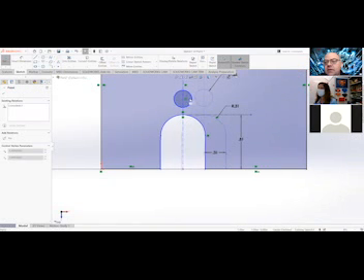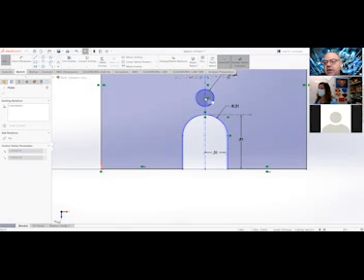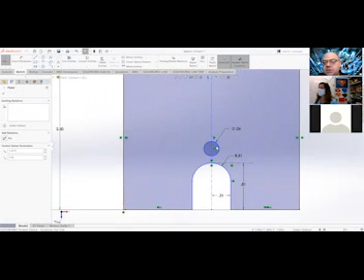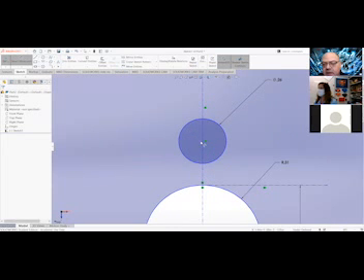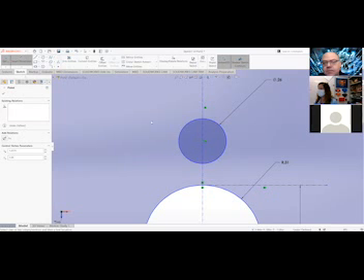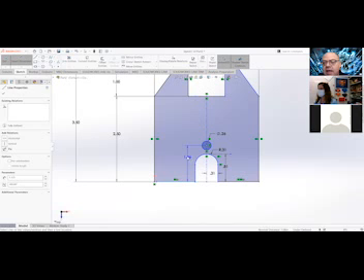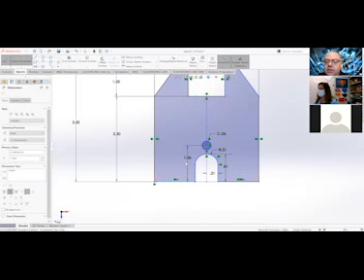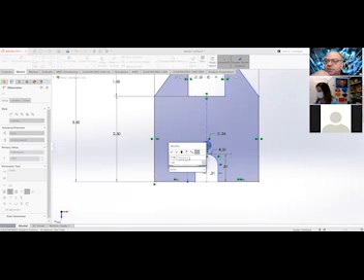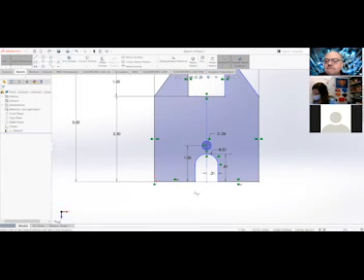If you're not on, whoa, what? That's scary. I got to fix that. Okay, so if your circle isn't drawn on, is it, let's see. Yeah, you're on the y-axis. You just need to move it. So the smart dimension goes from that little plus in the center. So we want to get that. And then the horizontal point down below. And then you force in the point, the 1.06. And that moves it to the right position. So that's there. Okay.